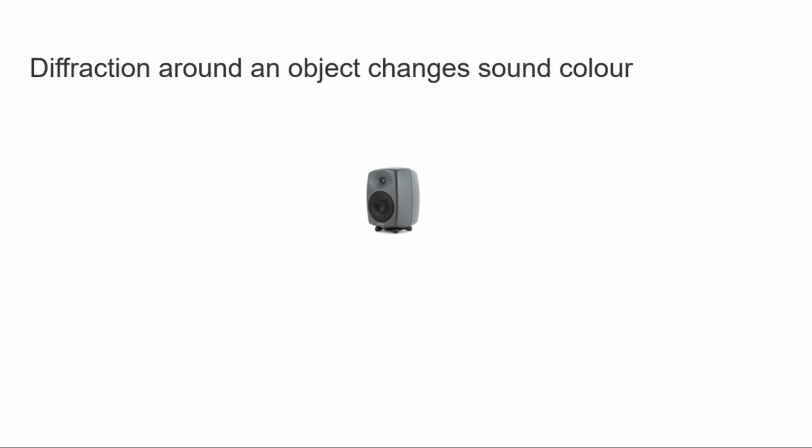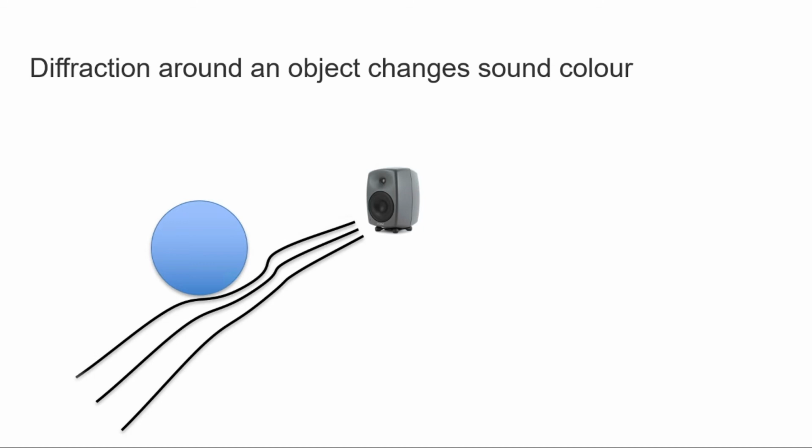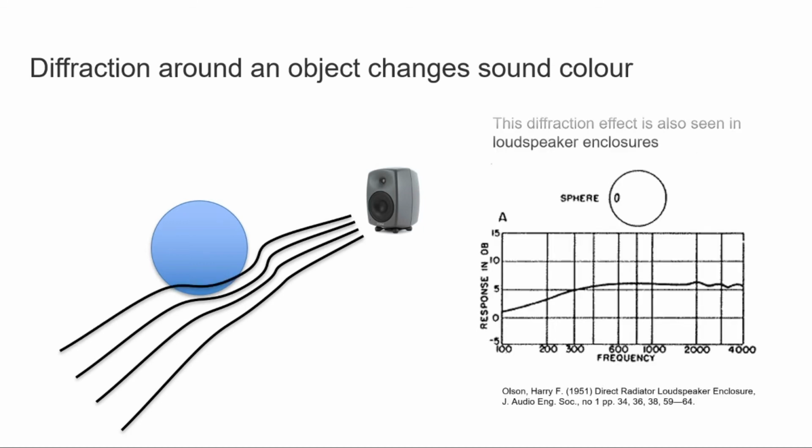The explanation to the common factor can be understood by considering an object in the sound field. Close to the object, the pressure at certain frequencies goes up when the audio diffracts around the object. This is also familiar in early studies of the optimum loudspeaker cabinet shape, where diffractions are causing frequency-dependent magnitude changes and acoustic loading in this example of a spherical loudspeaker cabinet shape.